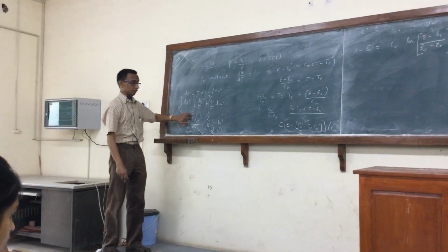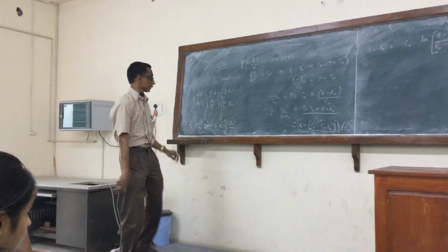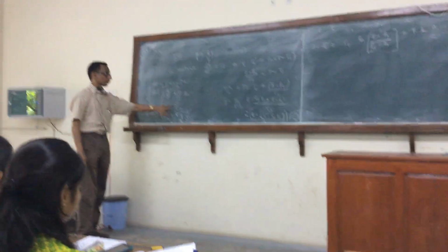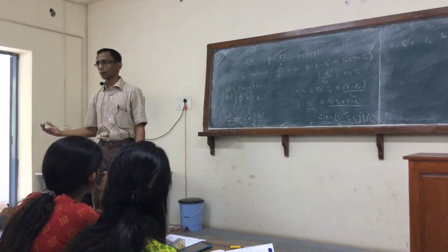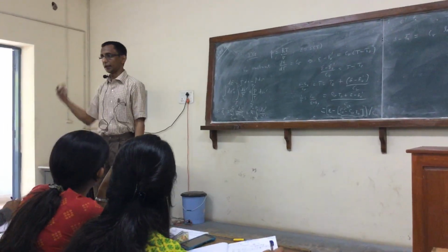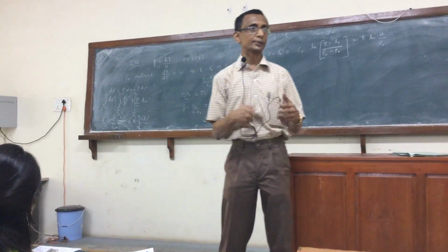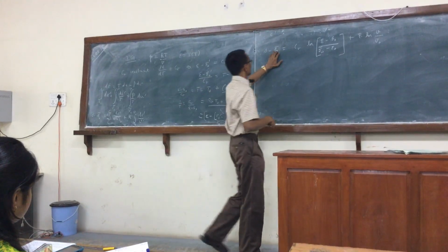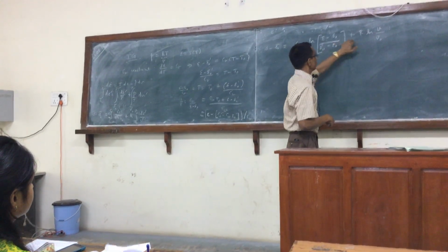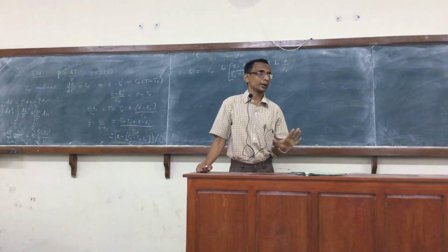So you could regard the entropy, internal energy and volume, the specific quantities, specific entropy, specific internal energy, specific volume, the particular state to be given by S naught bar, E naught bar and V naught bar. That's the correspondence. Right? So I am integrating from that some unspecified arbitrary fixed state to a general state at which I want the value. So you cannot avoid these constants of integration, as you will see. However, you see that I have introduced 1, 2, 3, 4 constants, but you can quickly see that only 2 are really needed.